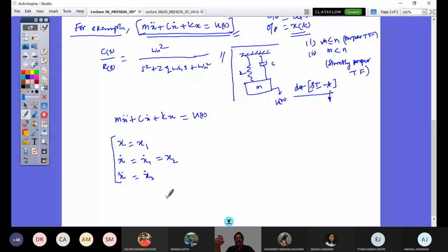Those two governing equations we were able to represent in the bicycle model in state space form straight away by putting in the vehicle parameters. But now when you have these three parameters, M, C, K, of a single degree of freedom system, which is represented by a second order system, I can represent that with this.